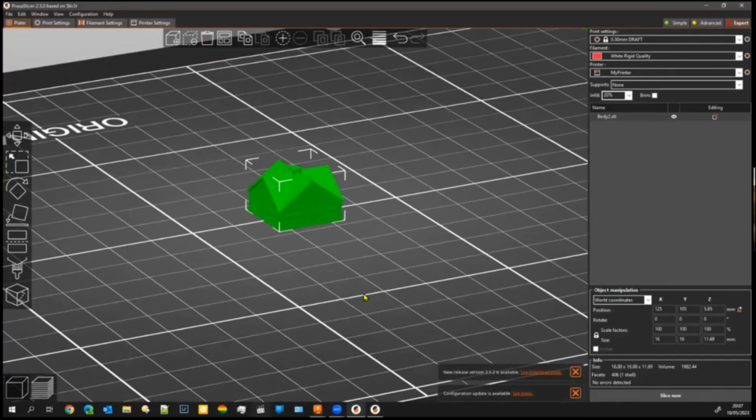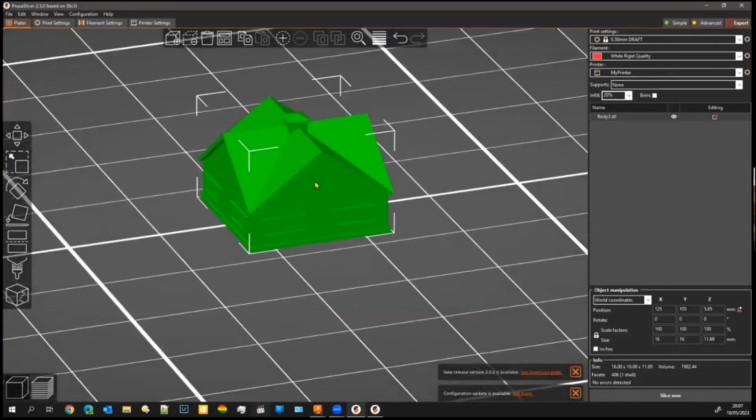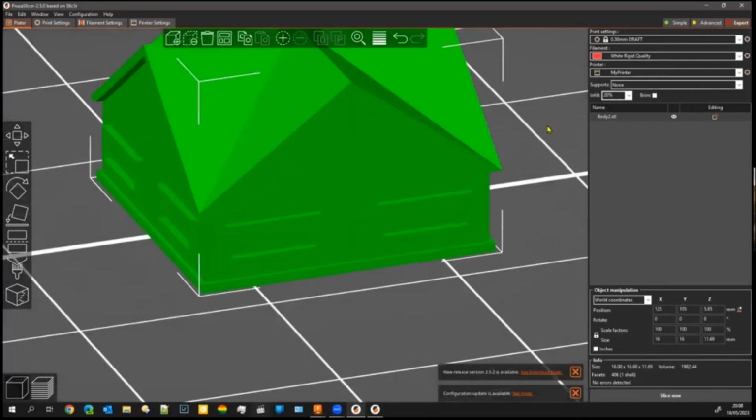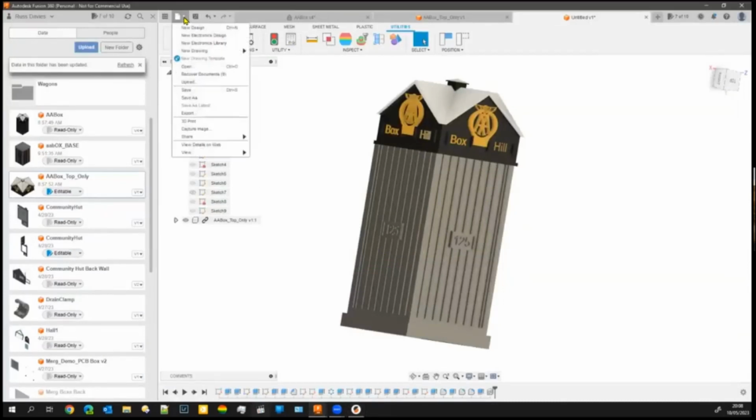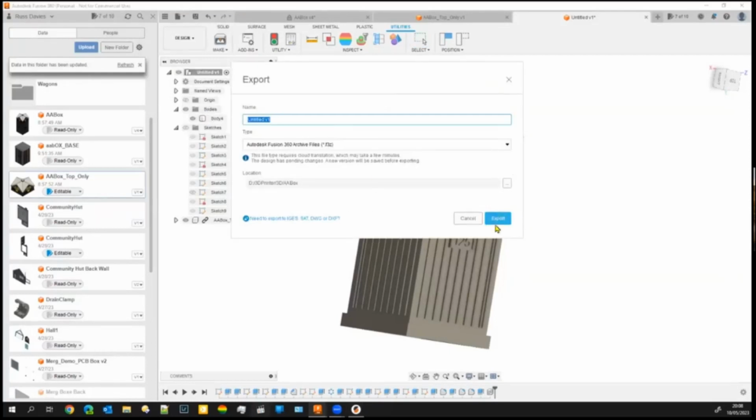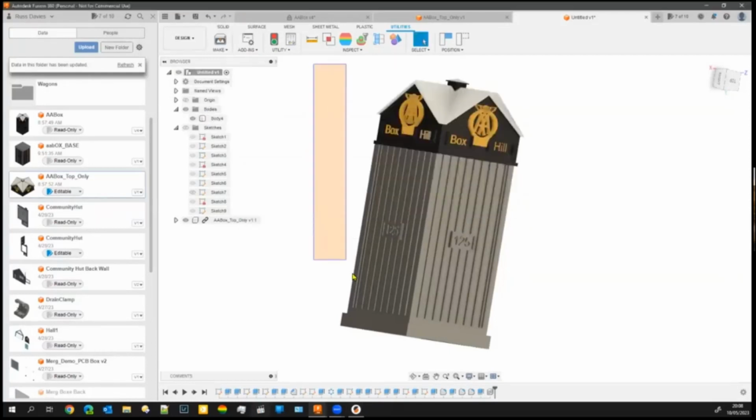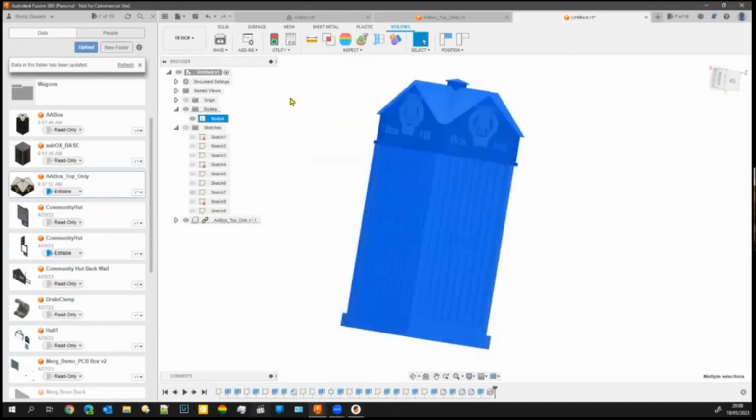But it's only taken the body, because if you remember, the AA sign was a separate body on the roof that we done. So what you have to do if you've got more than one body is you have to do what we call an export instead. So it's up to the file, it's export. So we highlight the whole thing first so we know what we're exporting.